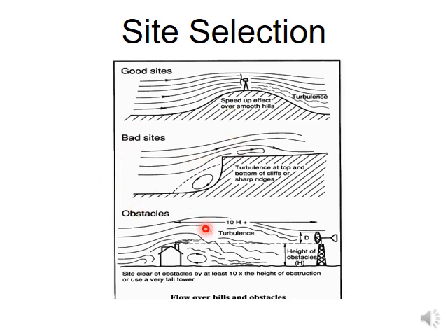So here, graphically and from some diagram, we are understanding where a wind turbine should be installed. Okay, so a good site means when the bottom surface is smooth and smoothly rising, and at the top of that we can install a wind turbine, because it will create a speed up effect over the smooth surface, like a converging nozzle. And on this side there will be some turbulence due to the boundary layer separation phenomenon, which we studied in fluid mechanics, similar to that.